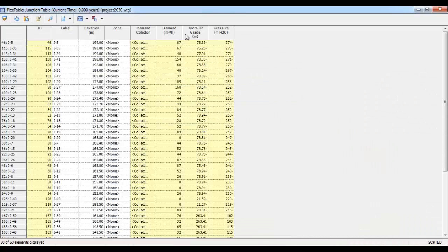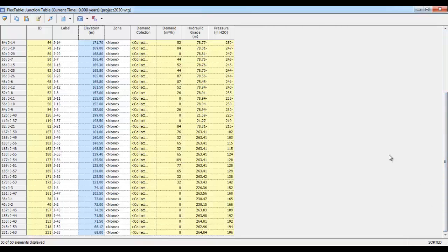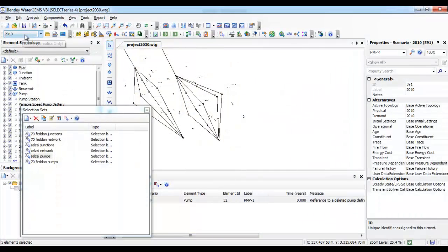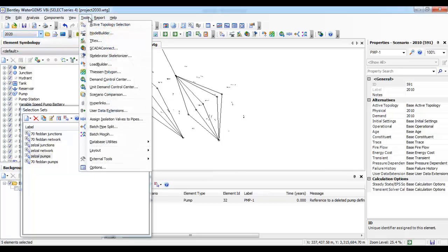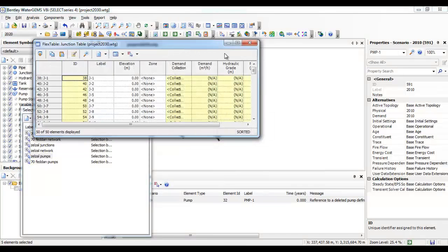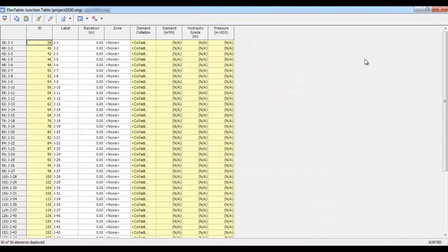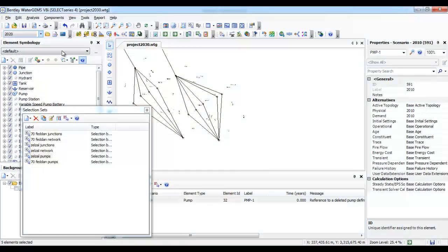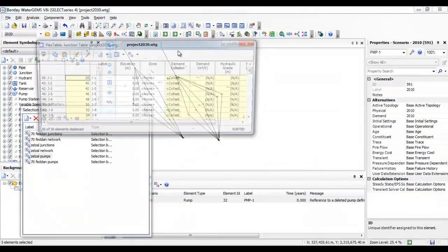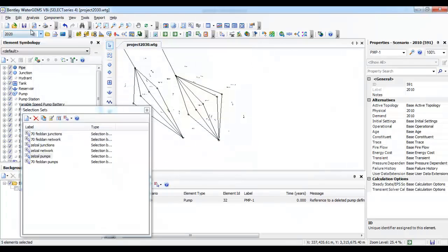When connecting the junctions, you will note that all elements have zero values at elevation. So the elevations are not set. What to do? You must define the elevation for all missed junctions in the other scenarios.